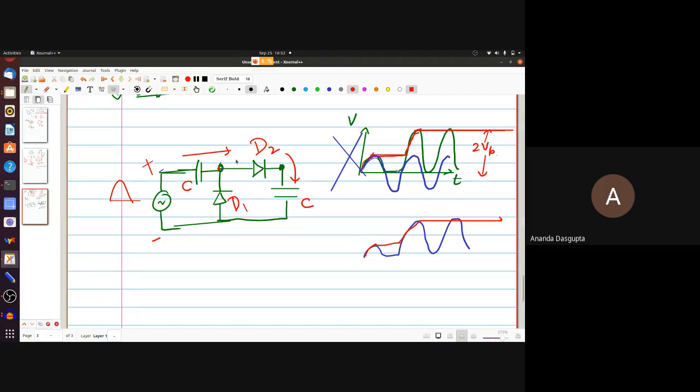Can you tell me what the voltage will be at these two points, this one and this one, which are of course essentially voltage drops across the two capacitors? First of all, will there be a difference in voltage between these two points? No. Why not? Because across D2 the voltage drop is 0, right. We are assuming ideal diodes, of course. We are making things simpler for ourselves. So these two points must be at the same voltage because D2 drops nothing because it's forward biased.